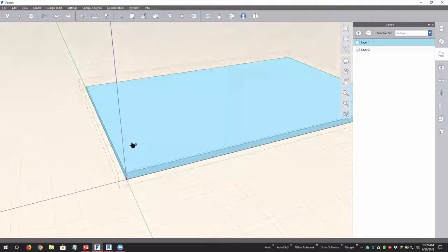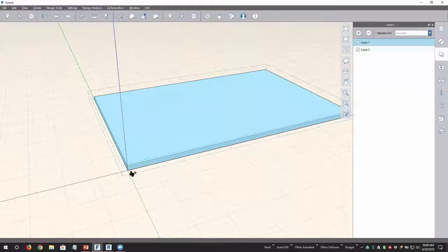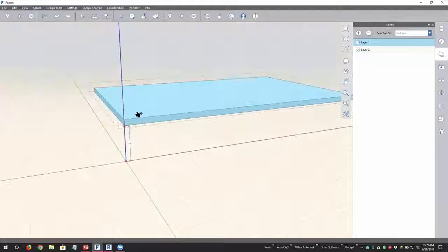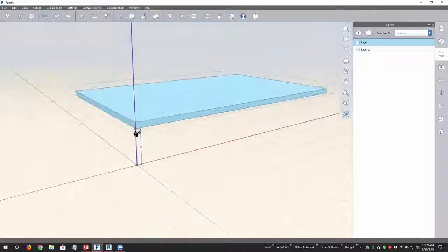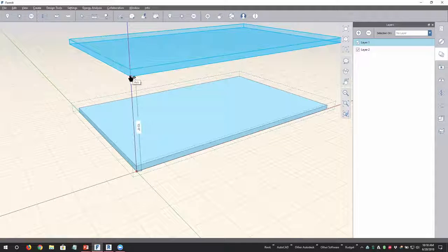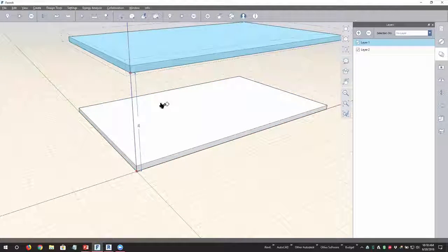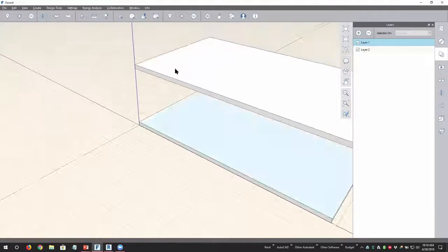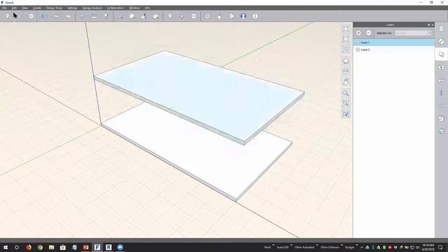And I'm going to create another floor up a little higher. So I'm going to grab this, and as I pull up, I can snap to the Z direction, and then tap Control to create a copy of it. Then I'm going to tab and make this 16 feet. So I can just create these different sketches, and then I'm going to create some other objects in here. Let's create some wall type of scenario.